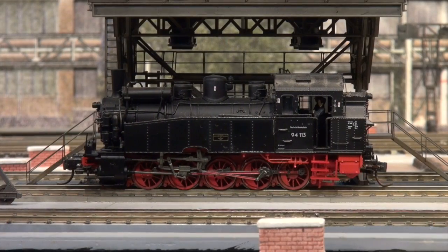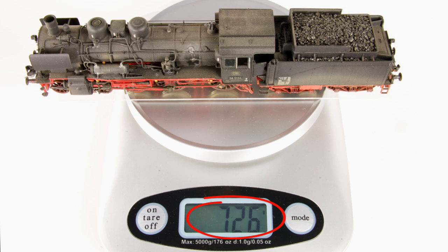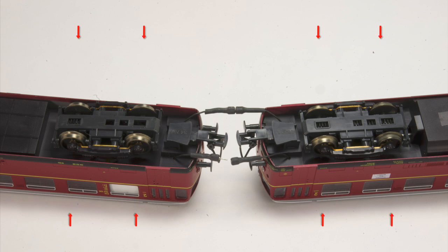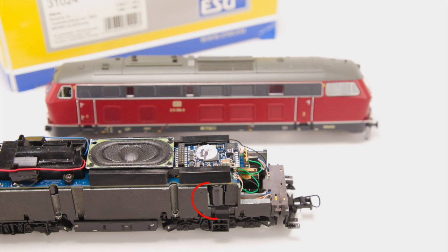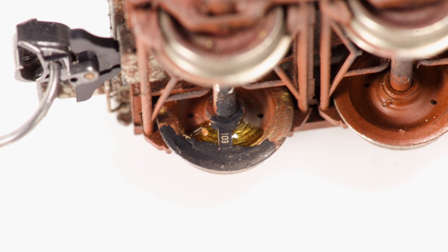To ensure the locomotives do not stall, I resort to different methods like using heavier locomotives such as this BR38 from Wayanad. All-wheel current pickups and jumper wires on this Kato rail bus and capacitors on this Izu locomotive all ensure stall-free operations. Rolling stock are weighted correctly as per the Fremo standards and resistors are installed to make them detectable on the layout.